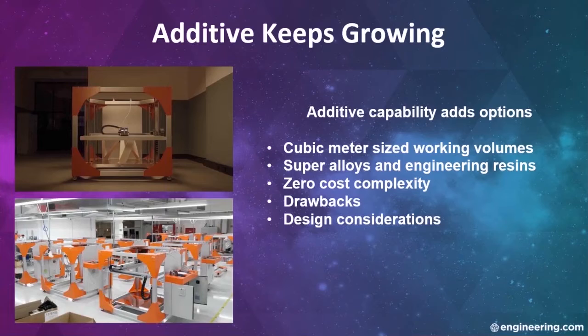Now, for both resin and metal applications, material selection is still relatively limited, but there's a growing list of copolymers, alloys, and even filled materials now available. On the plastic side, special purpose engineering resins are now available as the equipment manufacturers, the machine makers, are co-developing materials with major resin and masterbatch houses. On the metal side, the trend toward larger working envelopes is similar, and some very large-scale units are now commercially available using technology derived from the welding industry.